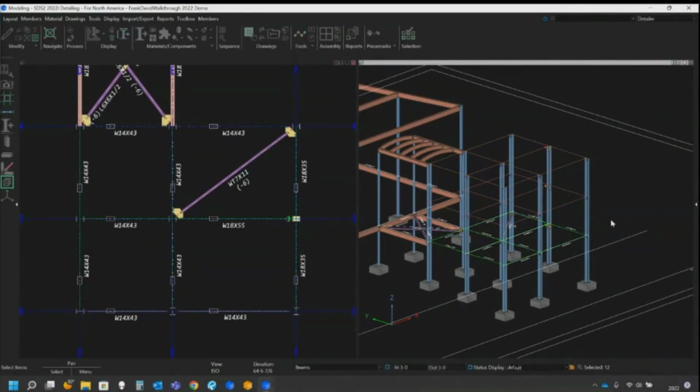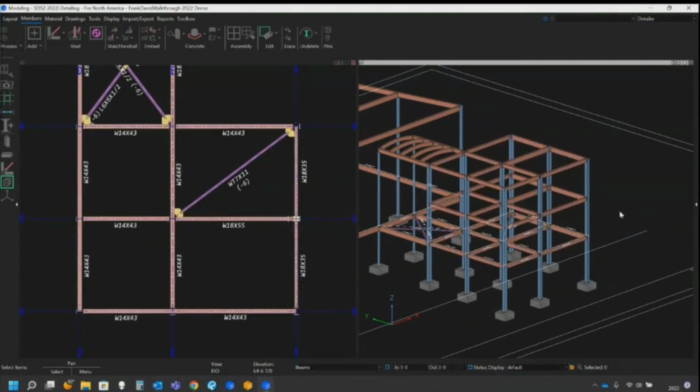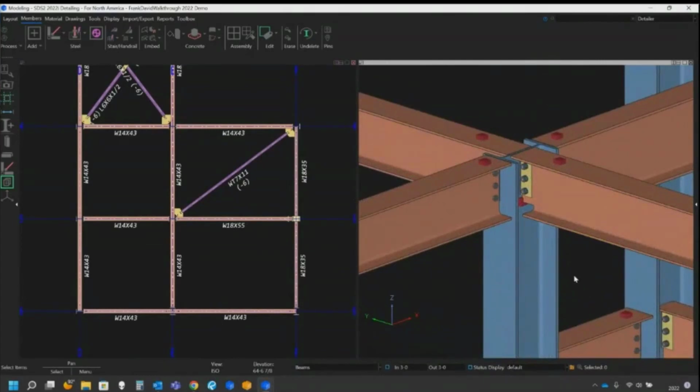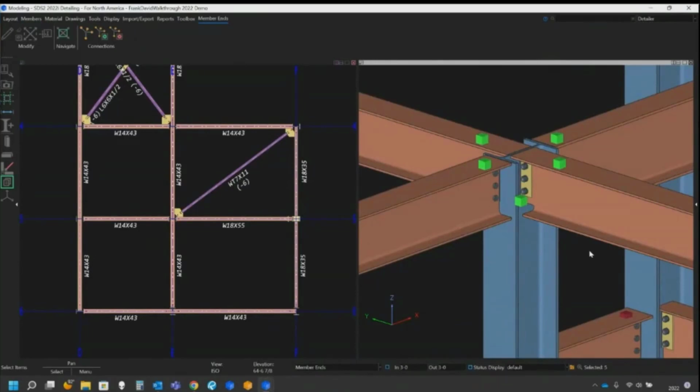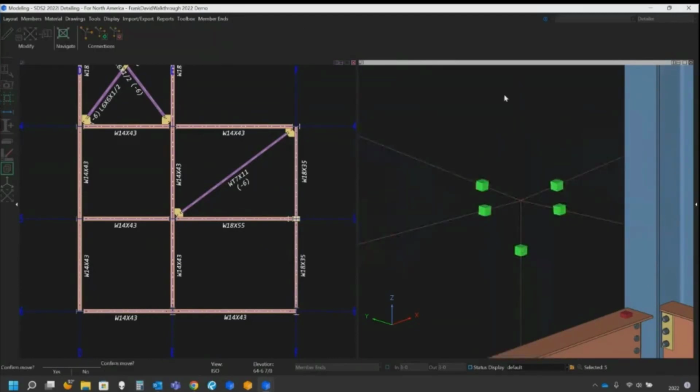Again, as I copy those, it's going to design all the connections. So obviously, as I make copies, the framing situation could change. So it does need to design the connection when you do that and make changes. And then where there's things like a sloping roof, I can easily grab my member ends and do a stretch on those, move those down 1 foot. So that creates about a 1/4 on 12 pitch for my roof.